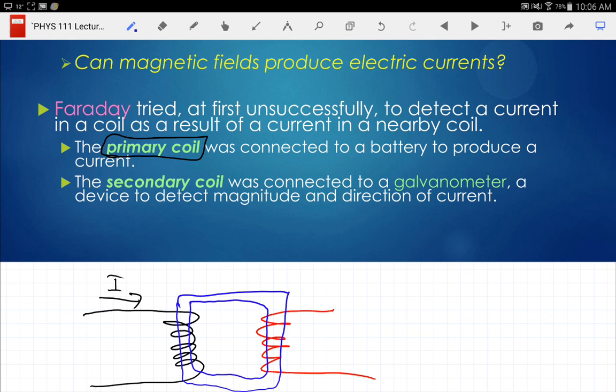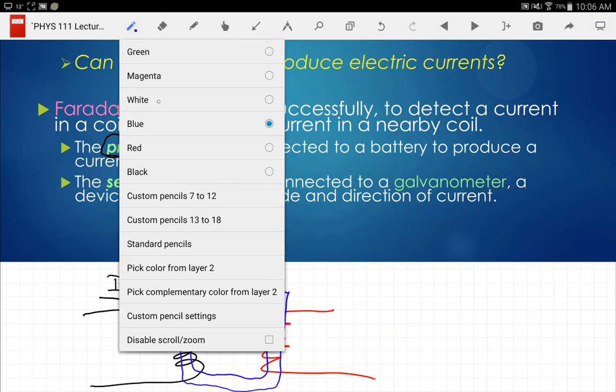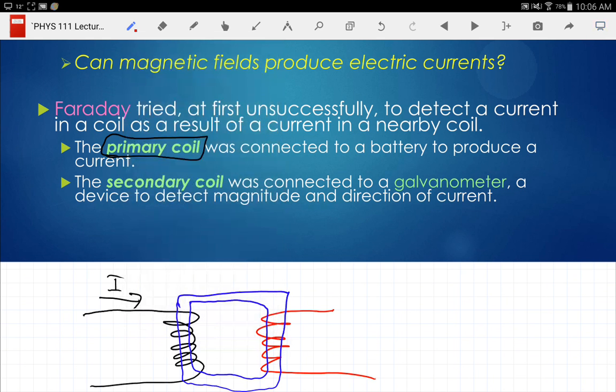If I have wire that forms a closed loop, I will have the magnetic field from the wire cause the other parts to also realign. So what it does is it keeps the magnetic field almost entirely inside of this loop. So the magnetic field is staying inside of this loop. So the magnetic field that I create on the primary, the black coil, then is also going through the red coil.